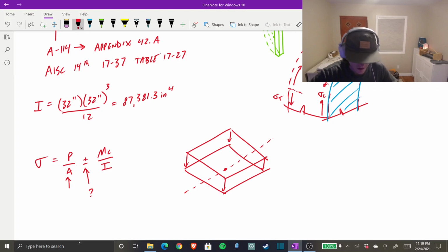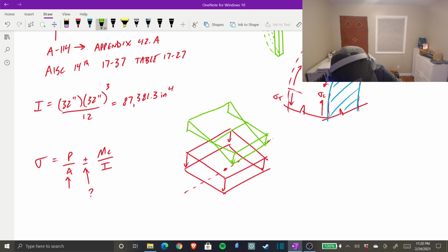So you have a total force divided by the total cross-sectional area. Easy, right? Then if I go green, we need to represent the moment that is introduced into our cross-sectional area. Well, that is not an even distribution. That actually comes across as that type of loading. And what you actually get is, depending on which way your eccentricity is being applied, right?